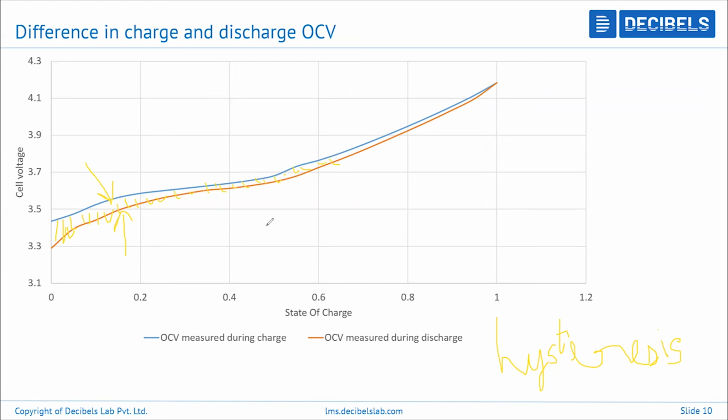Okay, and as and when the cell goes on aging, you have seen already that your OCV will drop. Okay, it becomes more and more. So your hysteresis band, or your voltage band within that small area, will go on increasing. Okay, so that is one important study that is performed over a very long period, say about 2000 to about 3000 cycles, and then the change in open circuit voltage during charging and discharging will be continuously logged. Okay, so the importance is that this voltage behavior will greatly affect the estimation of resistance and even the SOH, which is a big factor in battery management system algorithms. So when we're studying that, there has to be consideration of this as well. So this is another factor which has to be considered.